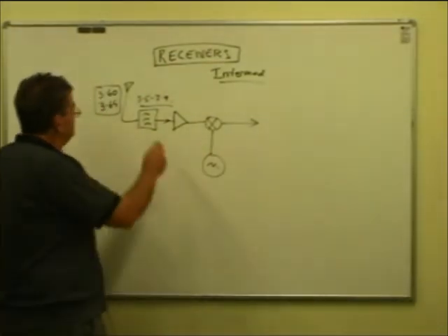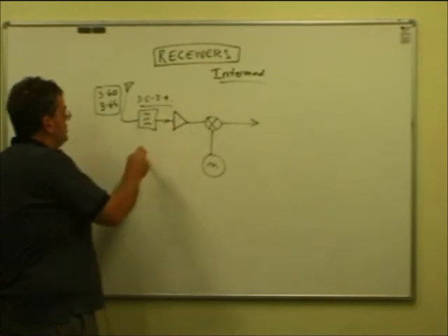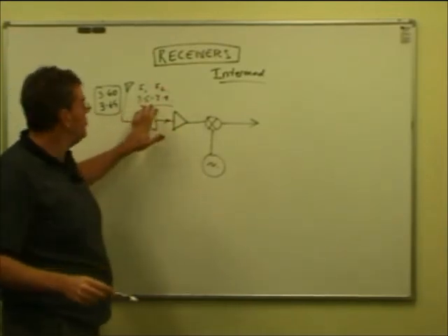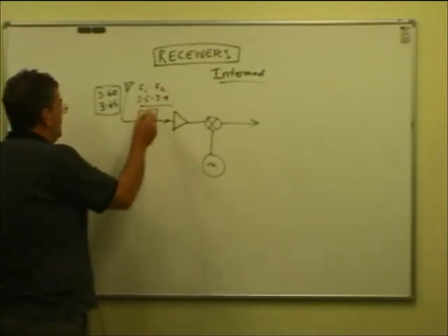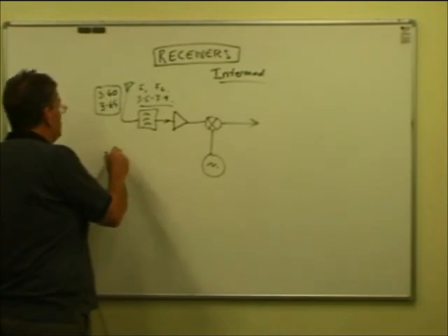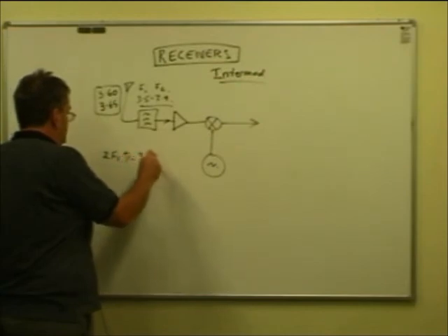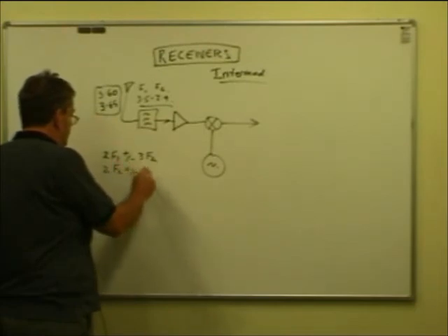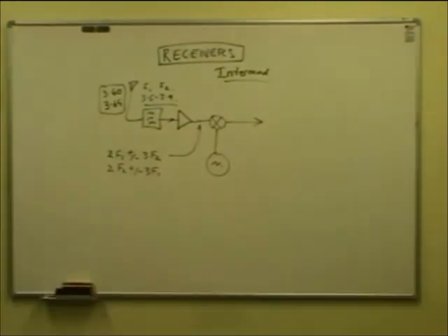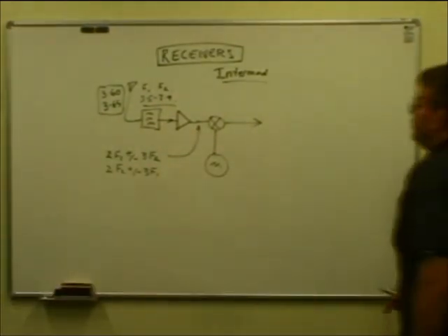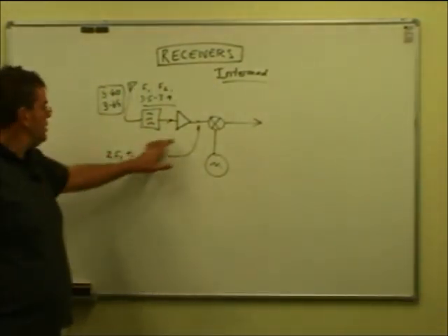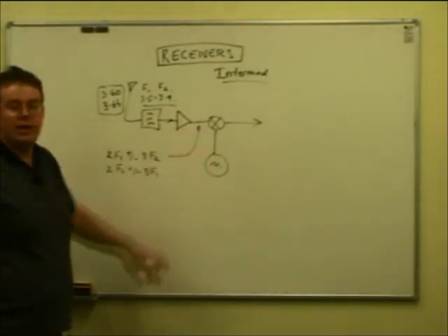What happens is these signals can combine, such that we call that one F1. Now this has nothing to do with the local oscillator. We'll just call this frequency 1, frequency 2, and we can get new things formed. We can get 2 times F1 plus and minus F2, or we can get 2 times F2 plus and minus F1. Now this is happening all the time, but fortunately, normally, in a well-designed receiver, the strength of these new signals created are so weak they don't cause a problem, or they're not actually appearing at all.